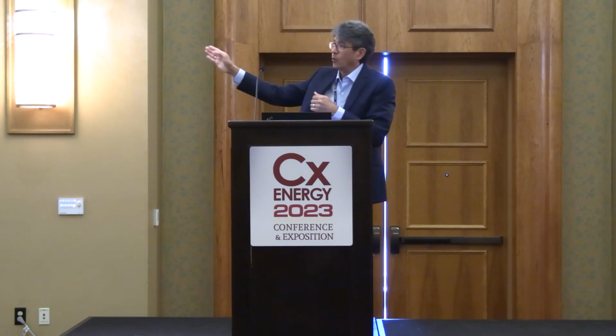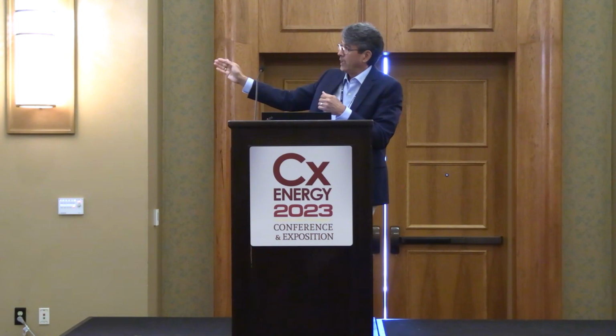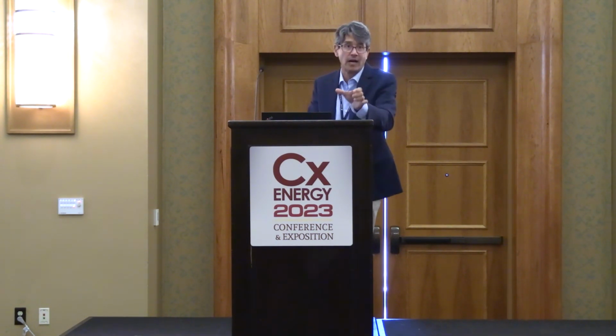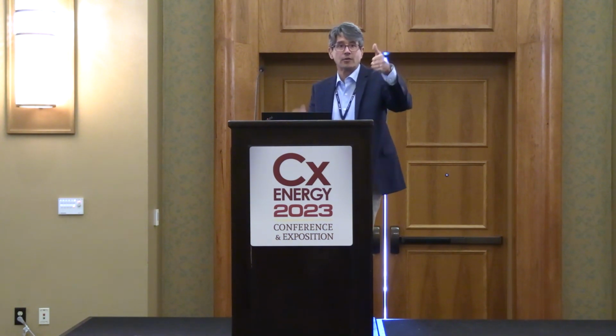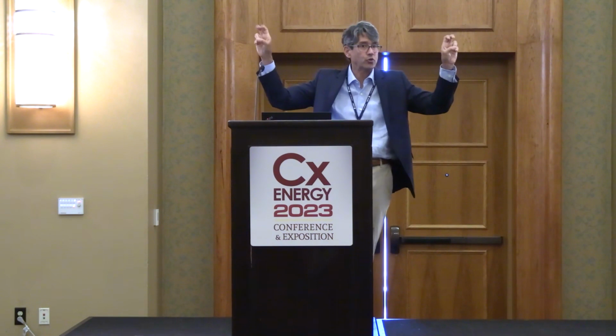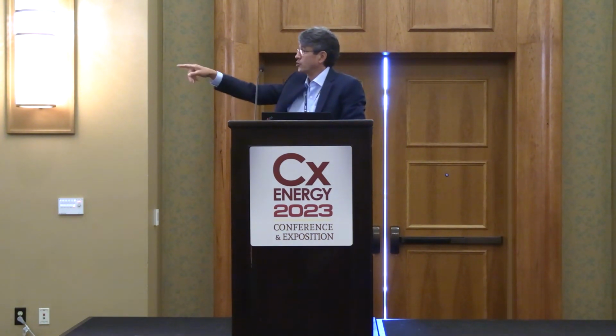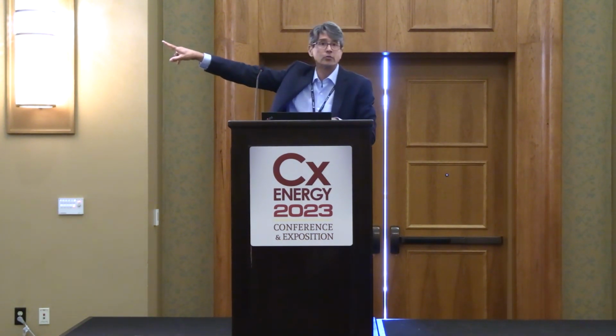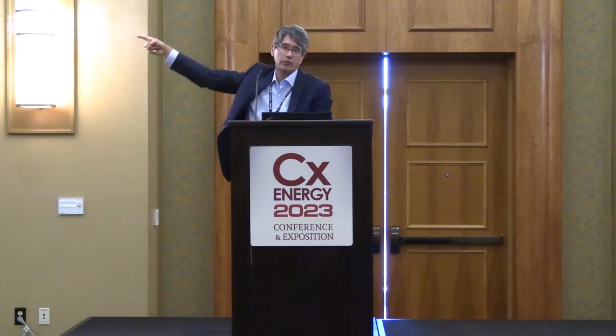We went door to door with all our pressures and correlated what pressures to what. So in the long run, they had a chart on the side: design this, their magnehelic was this. We measured this as our pressure drop across the media, but that pressure drop was actually between two of the access doors, not directly across the media.